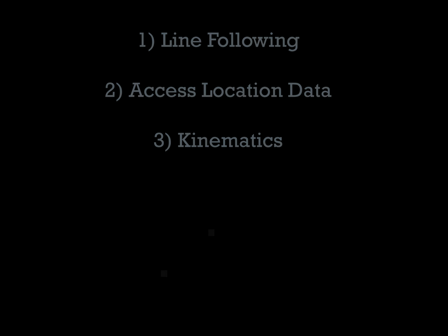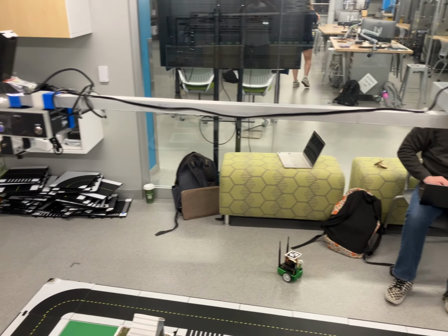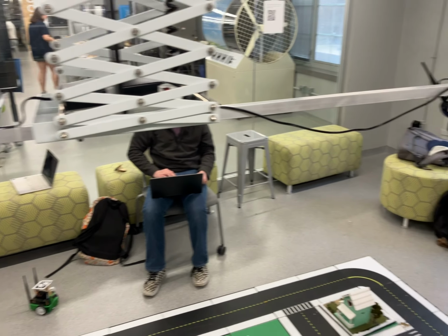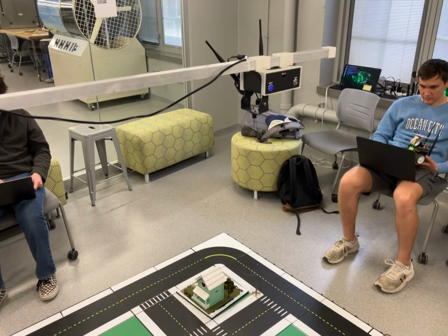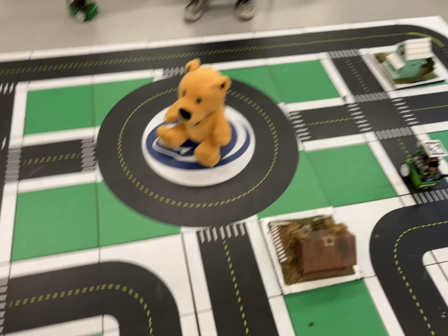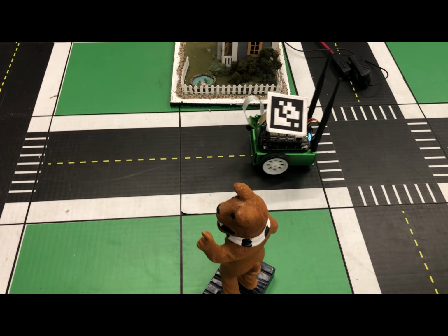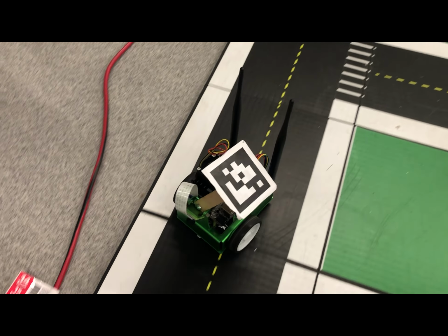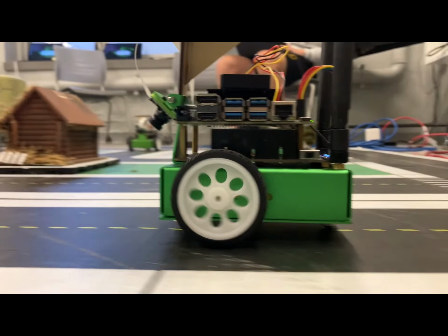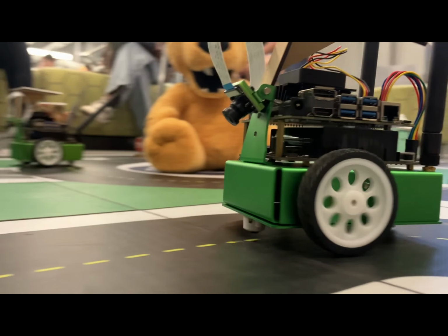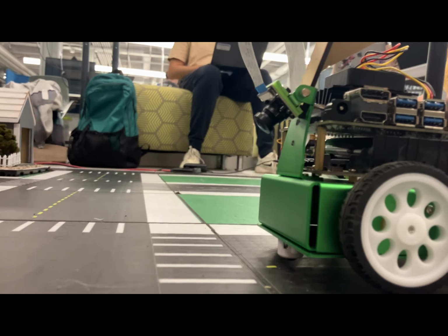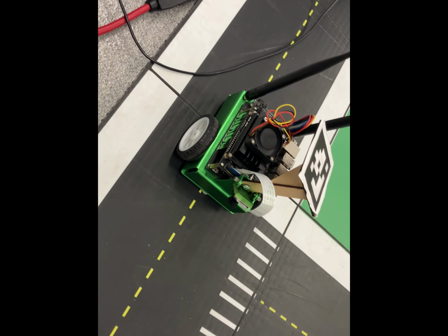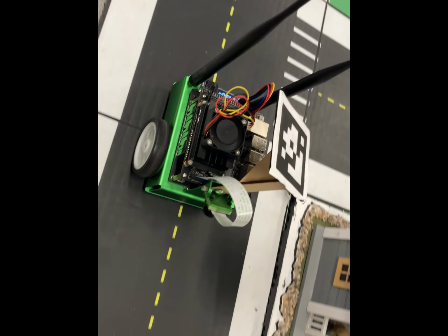In our program, the first thing that the JetBot does is communicate with the camera bot to retrieve its location using the April tag. Next, it makes a left turn that has been programmed based off of the desired turn radius from measurements of the course. After completing the turn, the line following algorithm described from Laboratory 2 begins, and the JetBot will continue to follow the line.